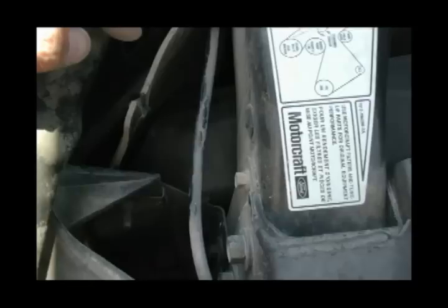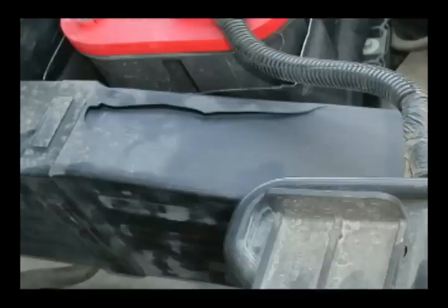The new snorkel pushed the insulation out of the way initially, but is now blocking the opening. Obviously, the insulation had finally weakened and sealed the air intake, which then cracked the duct. The crack in the duct allowed enough airflow for low loads, but would be restrictive over that.